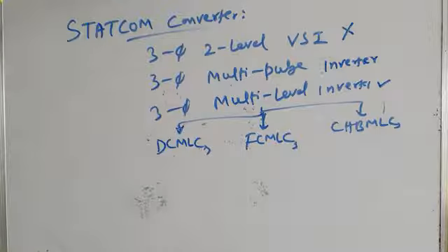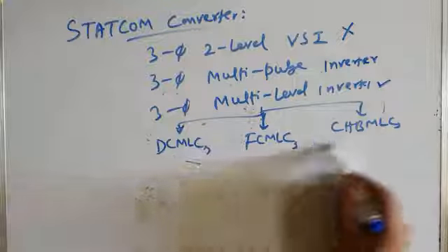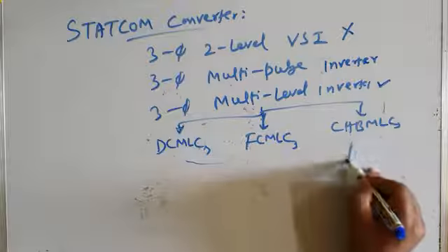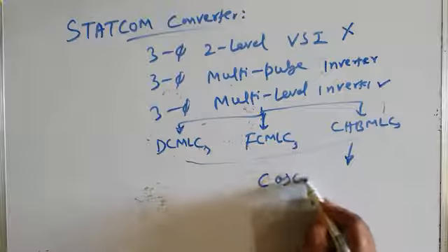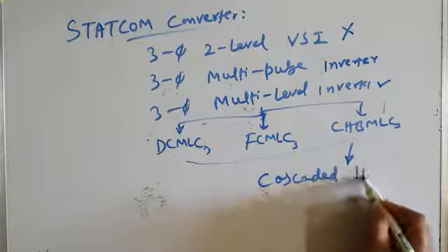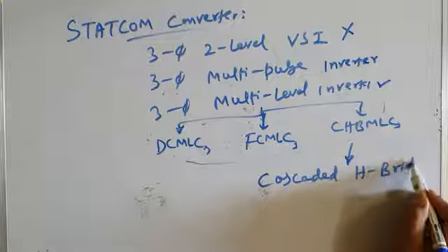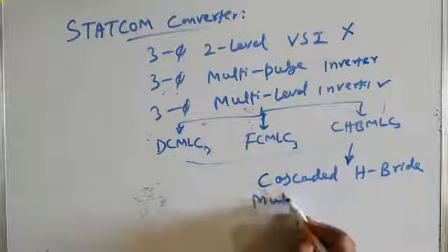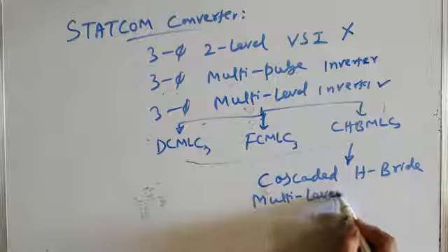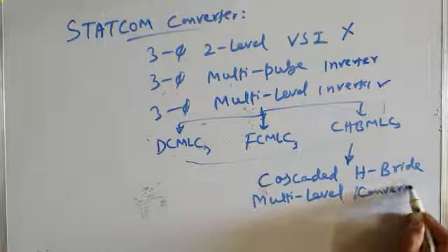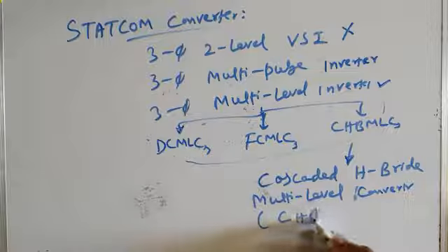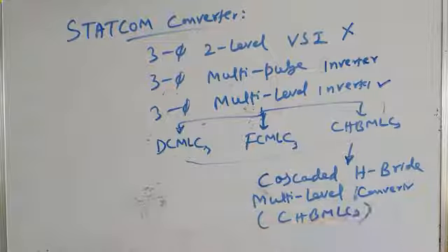And among the three types of multi-level inverters, the most popular is the cascaded H-bridge multi-level converter or inverter, CHB MLC, because it has the least device count.